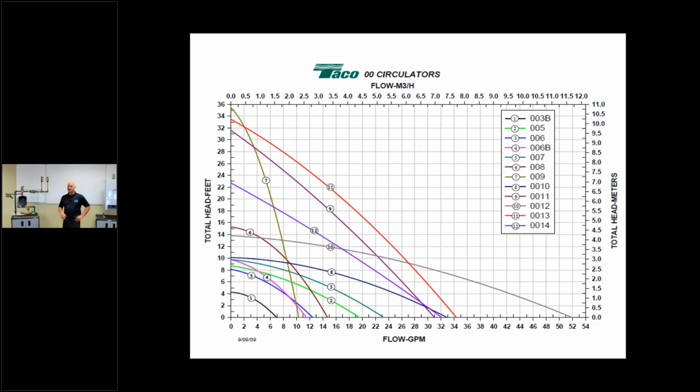This looks like it's a big system. Twin 300,000s. Nice. And it's got a good size B&G circulator on it. But again, we don't know how they piped it, primary, secondary. I would assume they did. You would think, a two-boiler system. Right, exactly. Because if that B&G is pushing through a Taco zone valve, it's probably making a little noise.